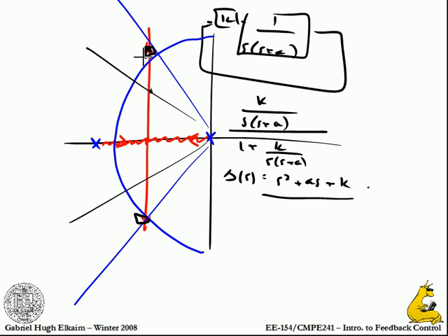Right. You'll see ringing. And once you see ringing, you're like, oh, okay, I'm getting into the dangerous zone, so I'm going to back off a little bit, and now I'm going to adjust the next knob to give me better damping. As I said, there are all kinds of methods for tuning PID controllers, some of which work. There's even a company that, if you send them your data, will send you back what they think are the optimal gains, and they guarantee that you can't find any better.